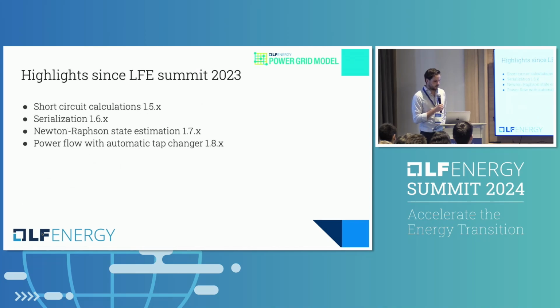And then some highlights since last year. So we did short circuit calculations. That's version 1.5 and above. So it's equivalent to the IEC standard. We introduced serialization in 1.6. So we have a way of loading and dumping your data to JSON and MessagePack datasets to easily store your Power Grid Model data.